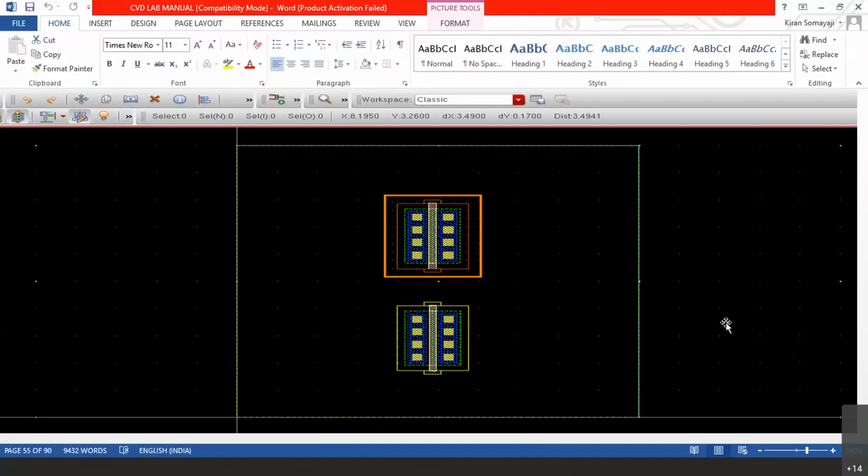But for connecting all these layers, seriously, high level of technical knowledge is not required. If he understands that which color corresponds to what type of layer, then that is enough. Only thing is, even a BSc person should understand schematic diagram and a layout. Now, this particular domain of VLSI design is called physical design. Physical design means taking a schematic diagram, you will have to prepare a layout. That is called physical design, where devices are physically present.